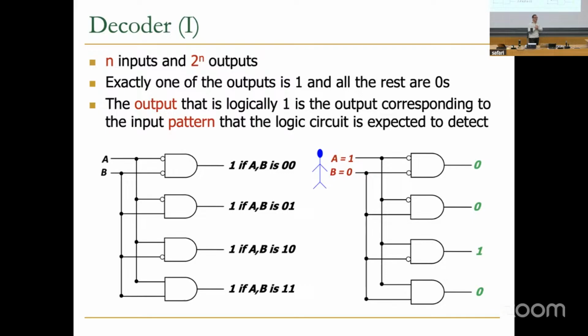So what's the function of this decoder? We can specify an address, for example. If your memory is, for example, let's say 1 gigabytes, I think that's 2 to the 30, no, 4 gigabytes, let's say, that's 2 to the 32 bytes. You need a 32 input decoder, and that specifies your entire address range, okay? We'll see that later on. So a decoder basically can tell you which part of your memory to enable so that you can get the data. This is called an address decoder particularly.